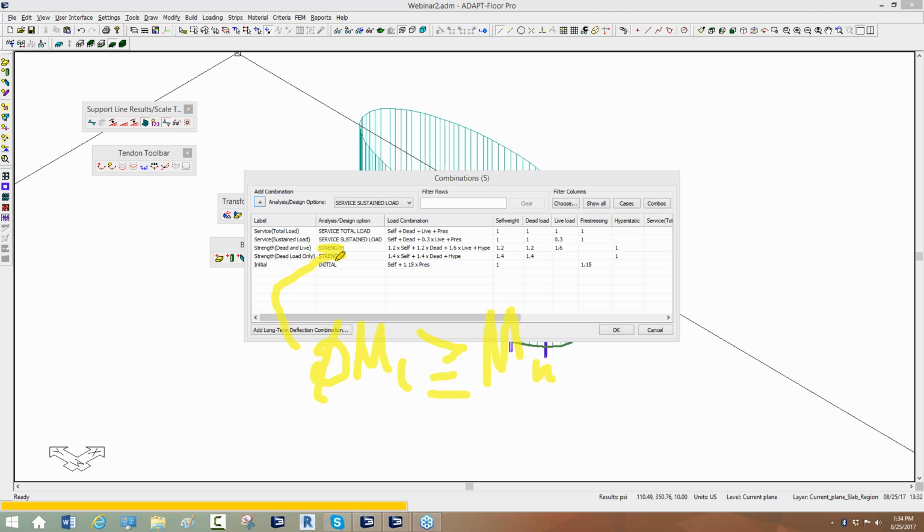For two-way shear, the program designs the shear reinforcement. If for punching shear the stress exceeds the code allowable, let's say we're using studs, which is 8 times square root of f'c, the program will report that that particular column has exceeded the allowable stress, and that's just an indication to the user that you have to do something to resolve that problem, whether it be add a drop panel or a drop cap, change the strength of the concrete, thicken the slab, whatever it needs to be done there, the user would be responsible for that.